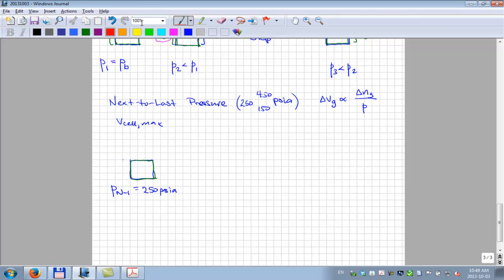And then the problem is that as we're trying to go down to 14.7 psi, somewhere along the way we max out the cell volume. But the pressure's still 123 psi, or something, 68 psi, whatever you like. The oil volume is on its way to shrinking down to final, but it's not quite there. You've got this gas volume here.